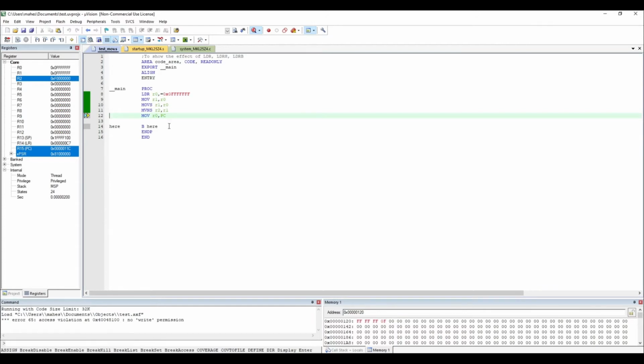That's exactly what happened. And similarly, the program counter, you can actually see the value of the program counter. This is the instruction which is getting executed. So if you see that, you can actually see the value which will come to R0. This is currently 11C. So if I execute it, you can see the next value, right? The program counter will store the next value which will come to R0. That's 11C. You will have the next one which is 120. Okay, so that's the idea.